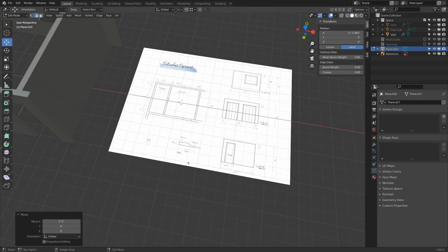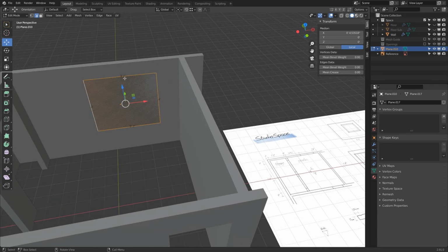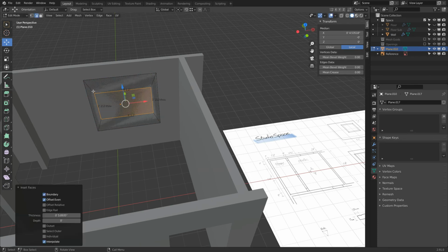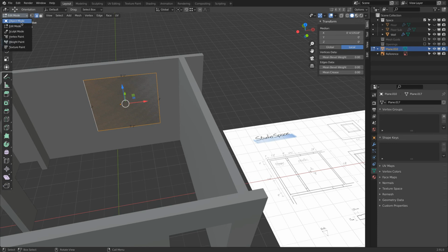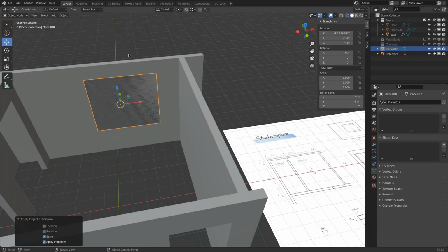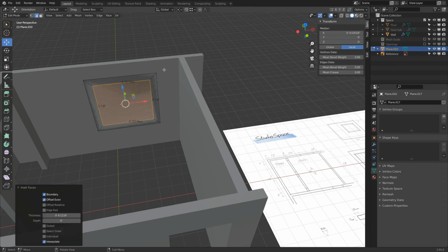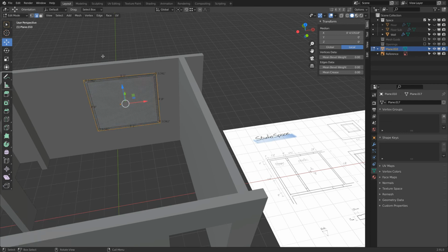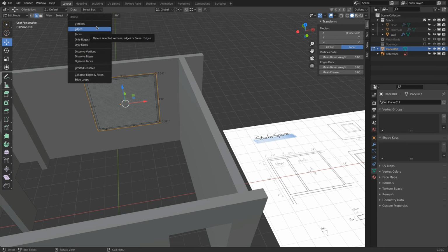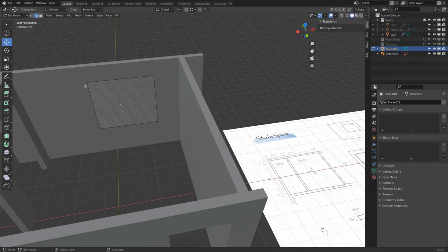And again here this is 6 centimeters. So how do we do this? How do we find this rectangle? In this case, with this face selected, we can press I. Oh, you see how this actually does an uneven offset. So Control Z, undo. In object mode, we need to apply the scale. Object mode, I click, and then here we type in 6 centimeters. Cool. This is the rectangle we need. Control I. In my case, I have all the edges selected. X and delete edges. Otherwise, select the correct vertices and delete vertices.